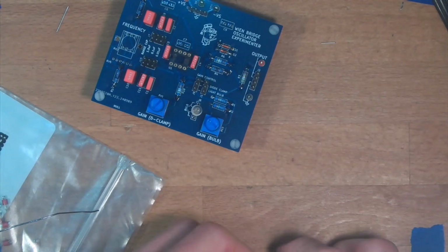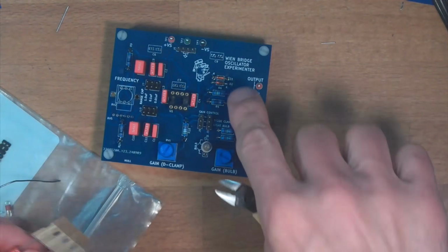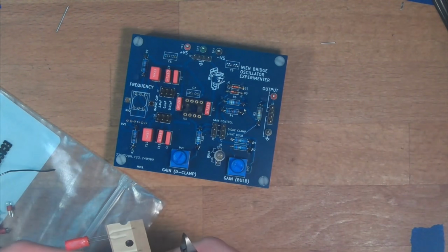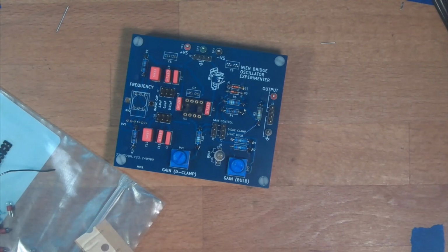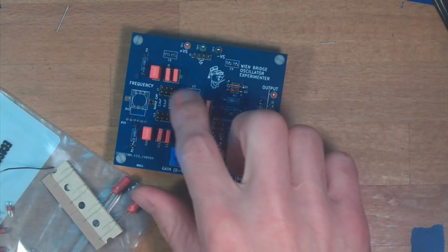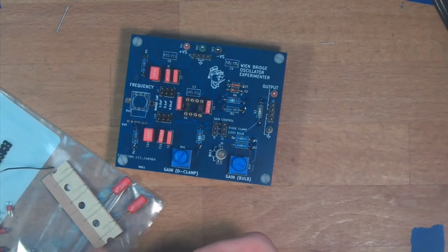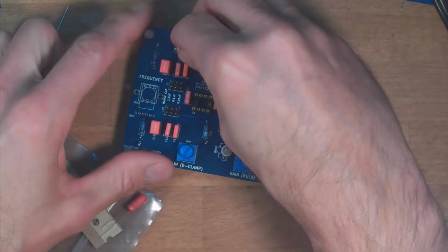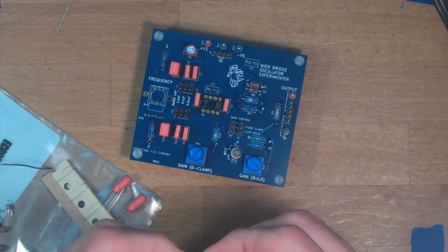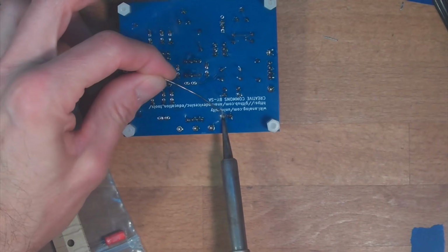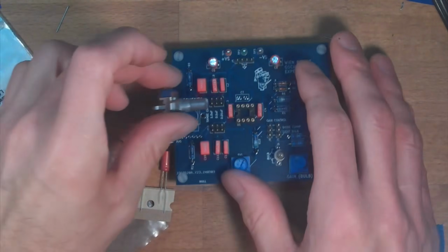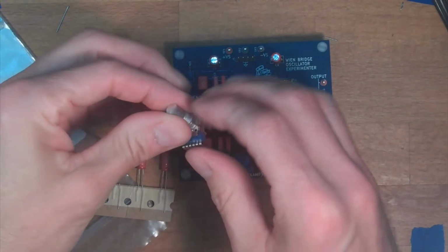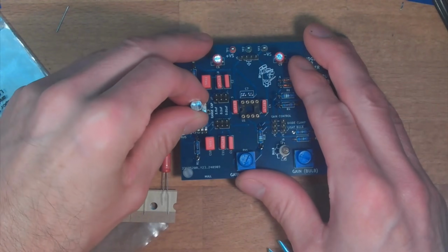Home stretch. I'm also going to put in, I left spots here for some larger electrolytic capacitors. So usually these little guys are enough to keep the op amp from oscillating, but you know what? Let's put some bulk bypass out here. So let's get our potentiometer in here, tallest item on the board.